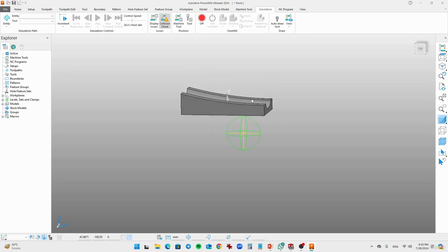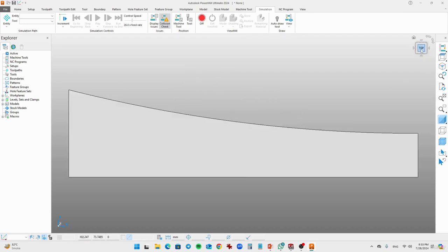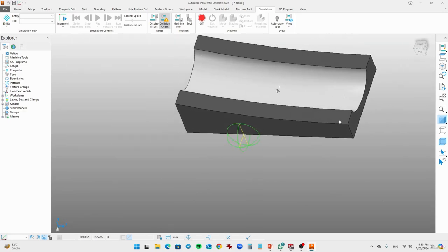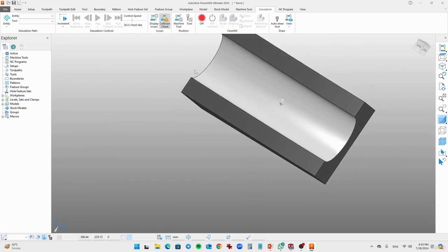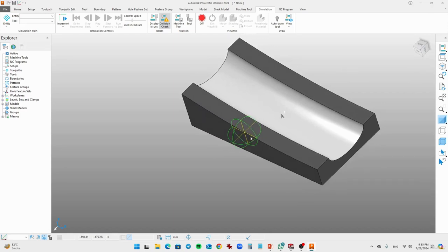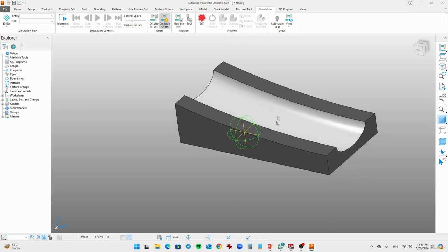One thing you see is that it's a top view, and you get this shape like that. Okay. So I want to do machining on this face. The highlighted face is the required job, and we have to perform the machining on this highlighted face. And my working coordinates are not according to this part.